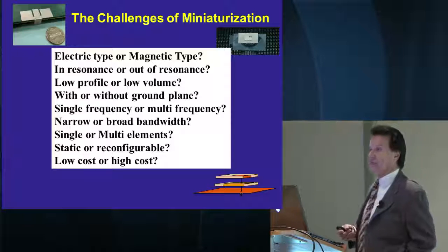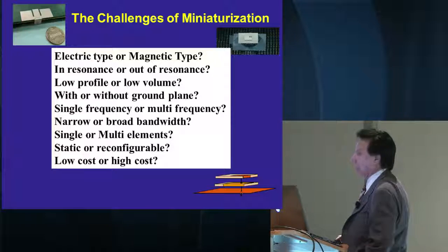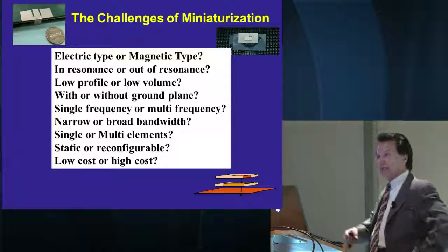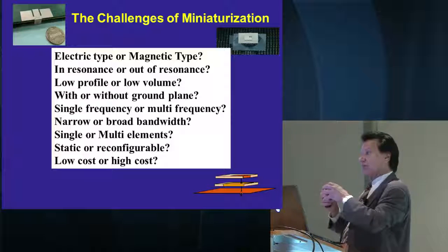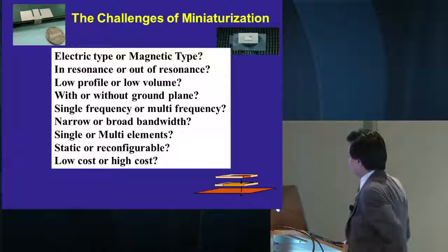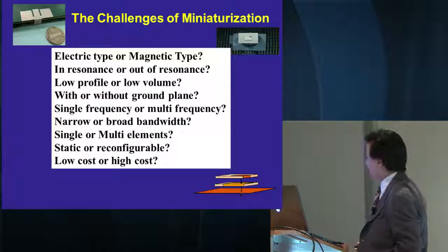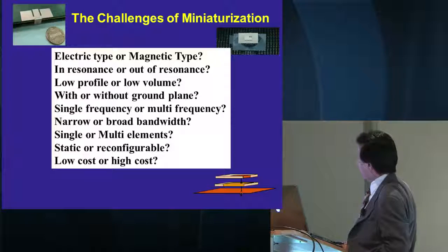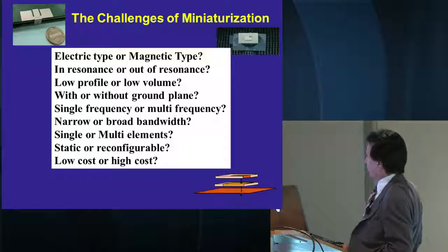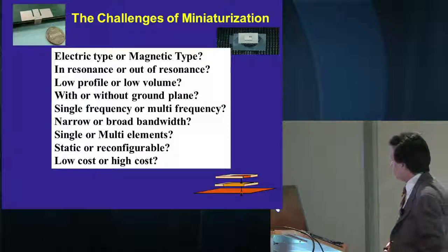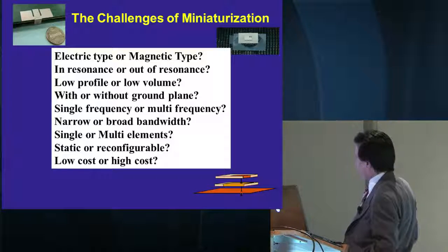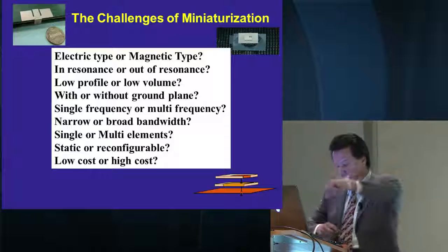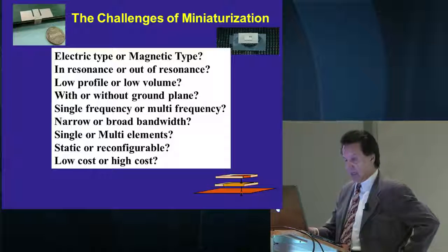Are these antennas in resonance or out of resonance? Are they low profile or low volume? They're different. Sometimes you design antennas which are very low profile, but may not be miniaturized in all three dimensions. With or without a ground plane: does the antenna have to support a ground plane, as patches typically necessitate? Are they single frequency or multi-frequency, narrow or broad bandwidth, single or multi-element, static or reconfigurable, low cost or high cost? These are all the questions that one has to address.